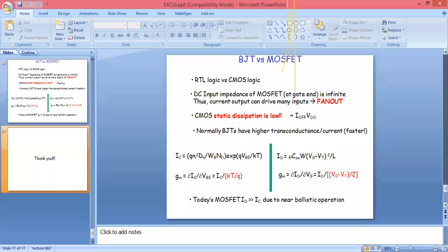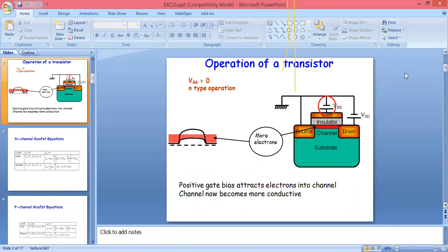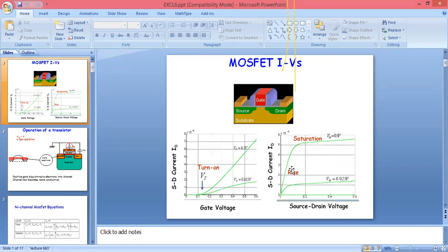In today's session, we have seen about the MOSFET and its analysis. This is the input characteristics. This is the output characteristics. If you are drawing the pictorial graph of input current with respect to the gate source voltage, then we can call this as input characteristics. And if you are drawing the pictorial graph for the output ID current with respect to the drain to source voltage for the N channel, then we can call this as output characteristics.